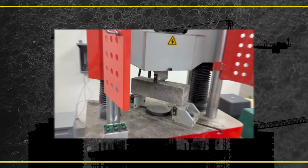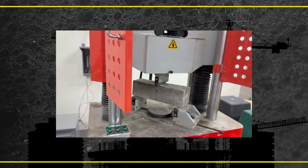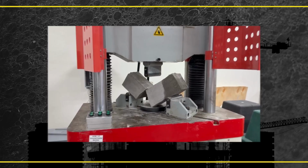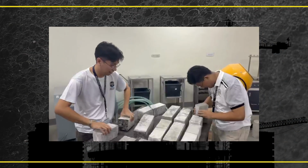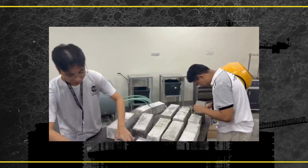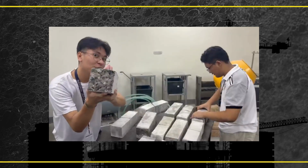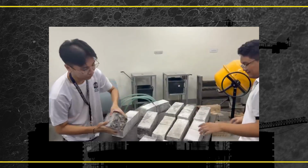After curing, the specimens were tested using a universal testing machine, UTM, to determine their flexural strength. During testing, we observed both the maximum load capacity and the crack initiation and propagation patterns, which provided valuable insight into how density affects failure behavior in foam concrete beams.